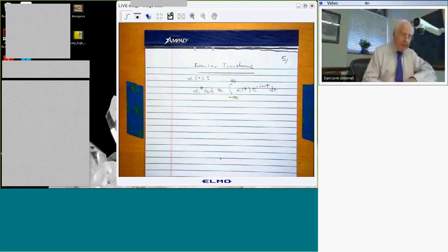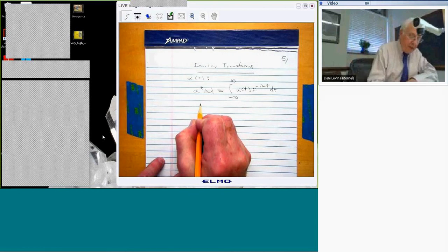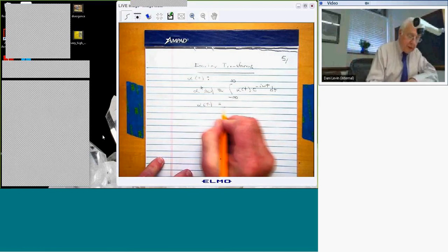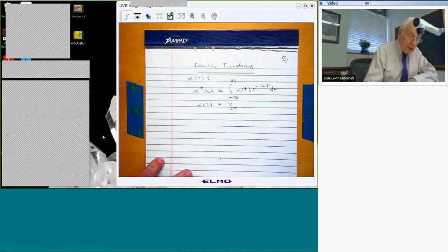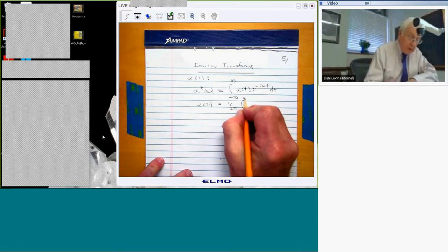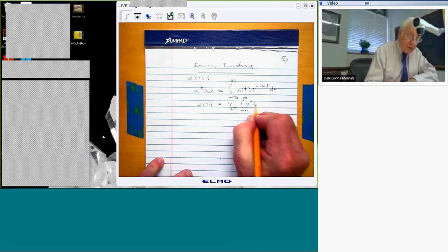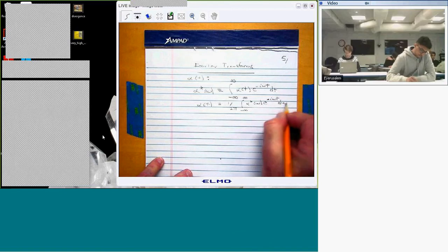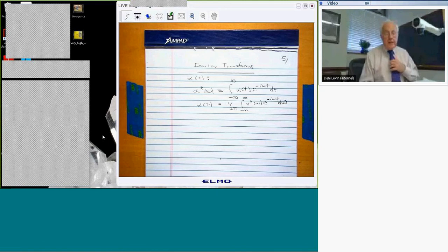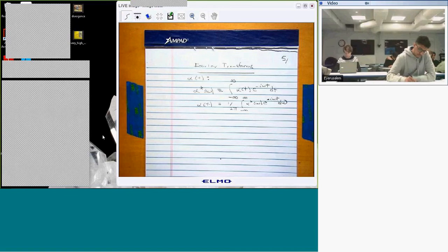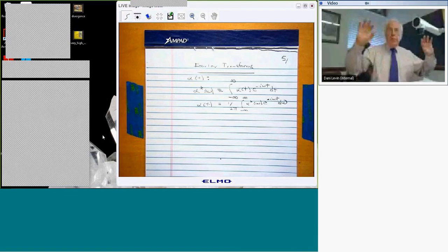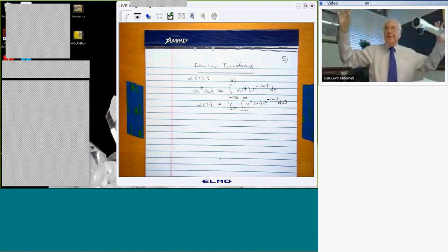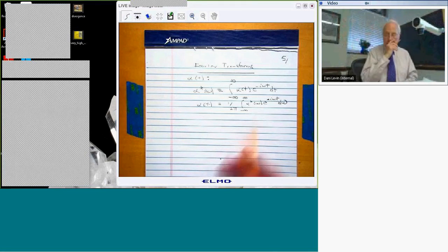And then the inverse of this, if I'm given alpha star, there's always a 2 pi somewhere. It's alpha star, which depends on frequency, and then I multiply by e to the plus i omega t, and integrate over all frequency, and I reproduce the function of time. And for linear systems, the virtue of this is that you can algebraically represent the relationship between the input and the output in the frequency domain, which means the algebra is simpler. And then all you need to do is invert and get the time history if you want that.